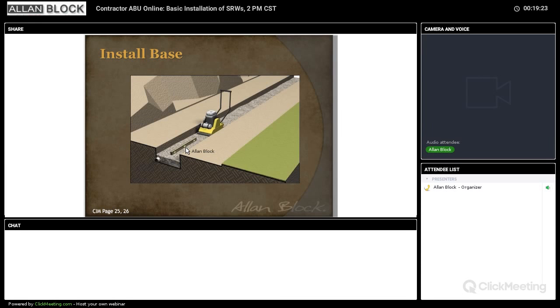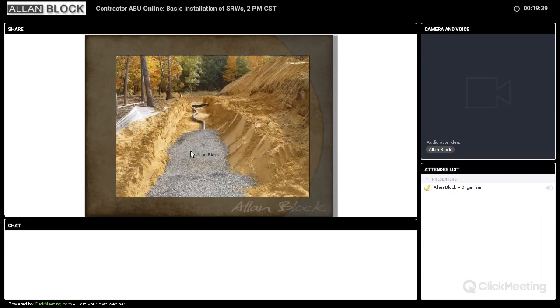Start taking care with your level right from the beginning. So when you're compacting and you're running a plate compactor, you're not looking for it to be perfectly level, because you're going to come in and fine tune it a little bit by hand as you're placing the block. But compact it well, and then fine tune the levelness under each block as you're building.